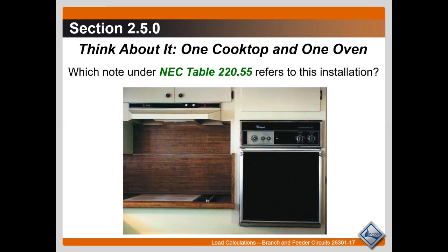So I'm going to scroll down till I see 33, and we're going to go with copper. It says I could use the number 10 for the 40 because it goes up to 40 amps. But in the industry, we go ahead and run an 8. Just because, like I said a while ago, we could put a 10 there and be within code, but typically for ranges we put an 8/4.